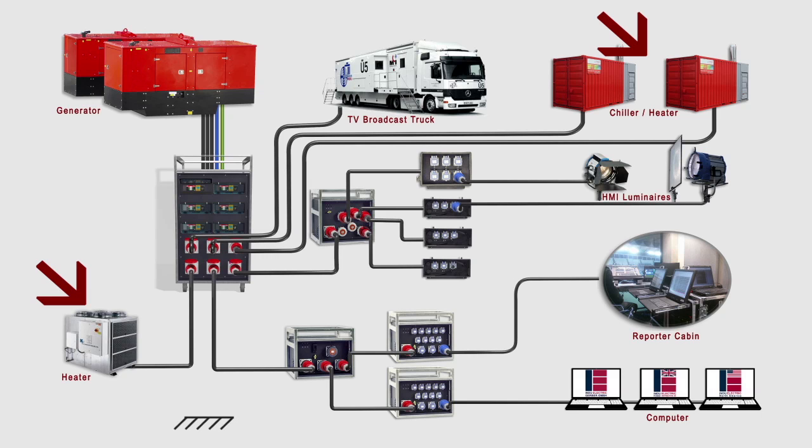Transient leakage current. Switching a circuit in stage lighting systems with many lamps can in addition cause transient leakage current. Depending on the phase angle, switching on a circuit results in rapidly rising voltage peaks. Because of the circuit's inductance, the same happens when switching off the circuit. Through the filter capacitors of the ballast devices, these sudden voltage peaks create a transient ground leakage current, which can cause the residual current device to trip when the system is first switched on.